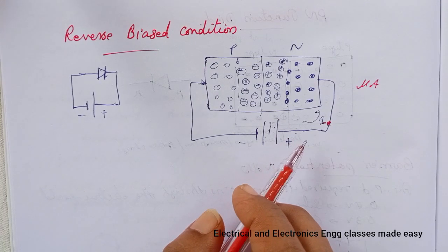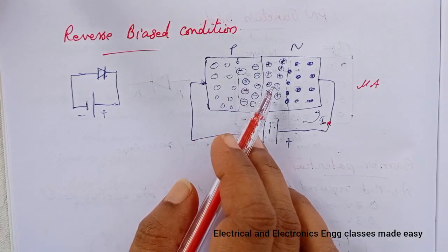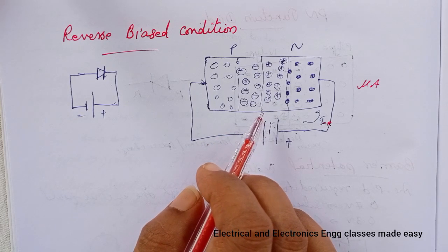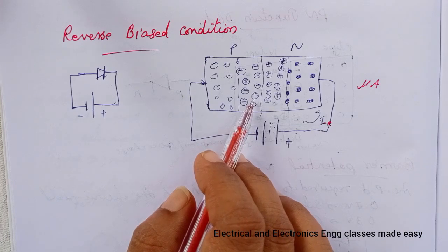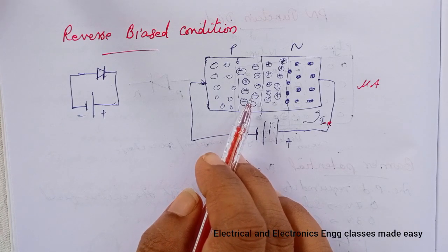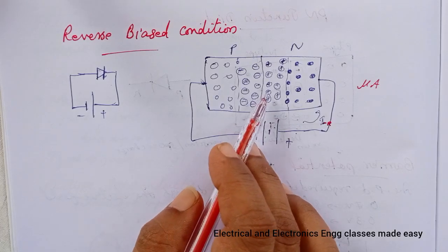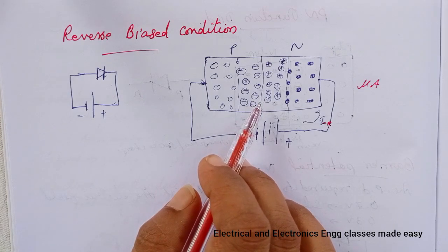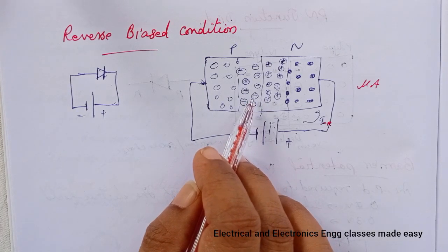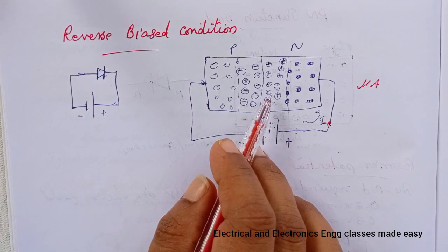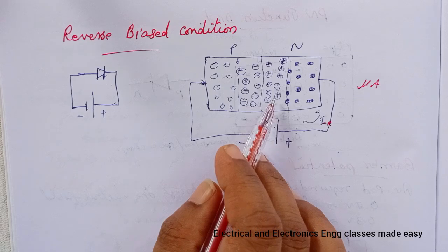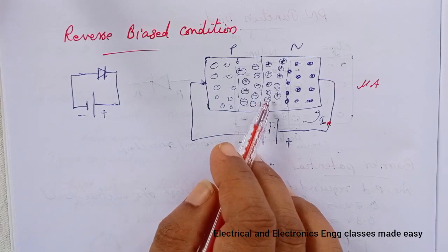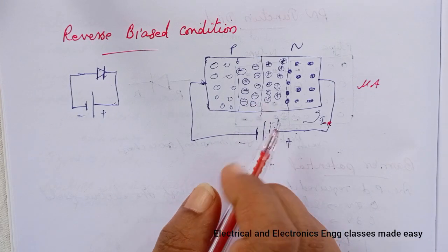And if reverse voltage is increased continuously, the kinetic energy of the electrons may become high enough to knock out electrons from the atoms, and these electrons available as minority carriers get accelerated due to high reverse voltage, and they again collide with other atoms to generate more minority carriers, and finally a large number of minority carriers move across the junction, breaking the PN junction. And when breakdown of the junction occurs, there is a sudden increase in reverse current, and this effect is known as avalanche effect.